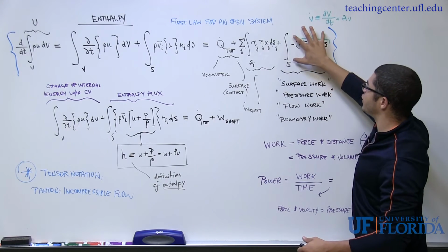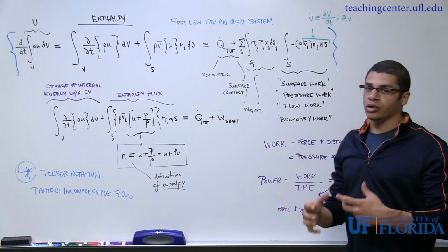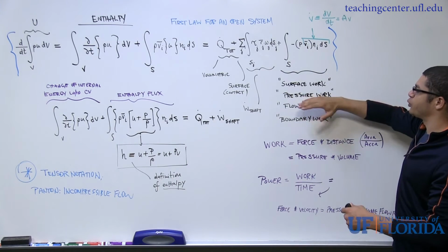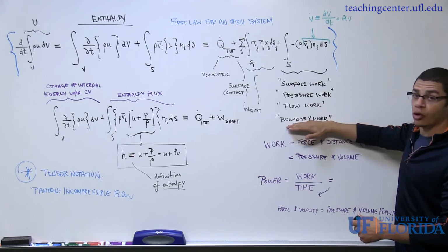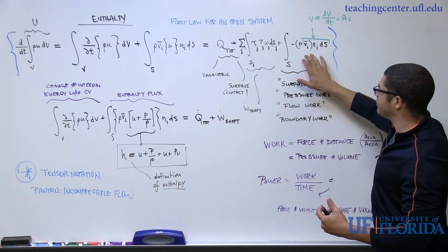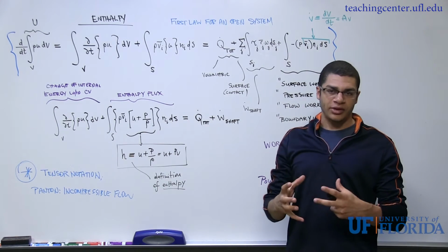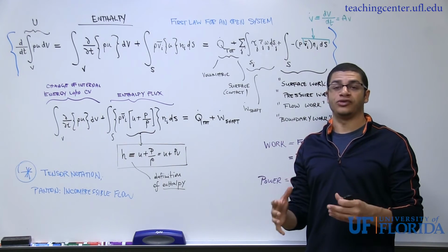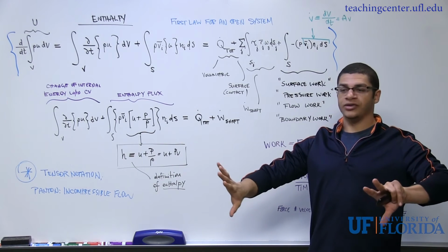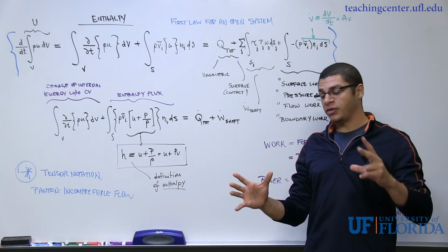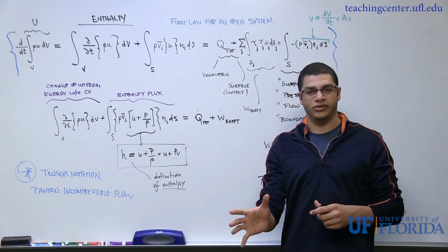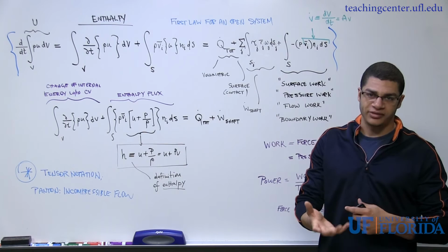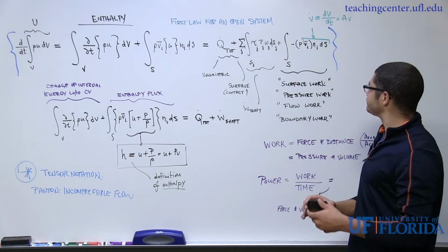This term relates the flow work, as I've listed here. Flow work, pressure work, surface work, and boundary work are all synonymous terms. That's associated with the fluid or substance pressure within my control volume, either displacing fluid that's surrounding it, so it's doing some work, or the fluid may be flowing into the system and doing work on the system itself by the same means. It's at a pressure and it's displacing some volume of fluid that's in our control volume.